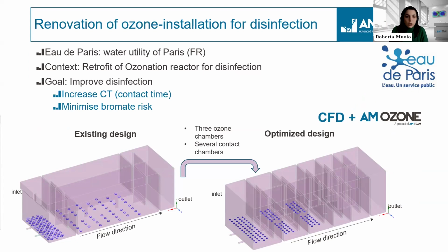So it's an ozonation reactor, and they had to retrofit or renovate their ozone reactor. The goal there was really to improve the disinfection by maximizing the contact time of ozone in the water, and at the same time minimize the bromide formation risk.